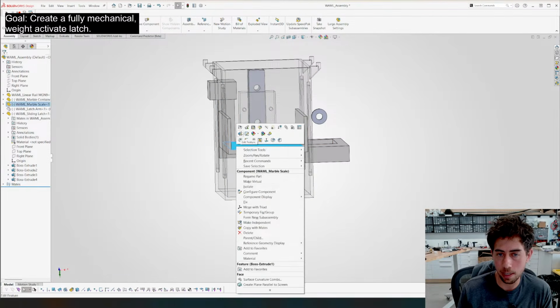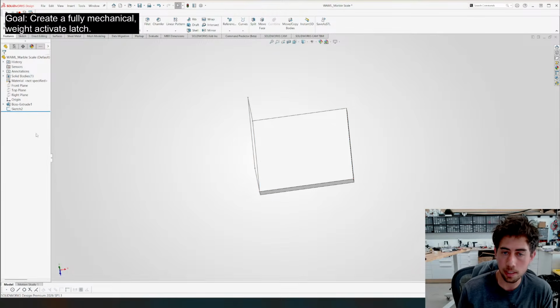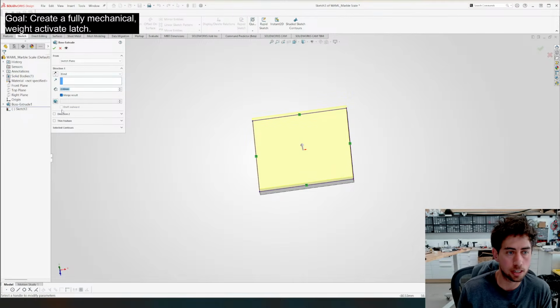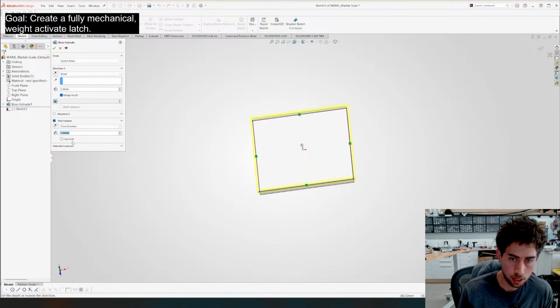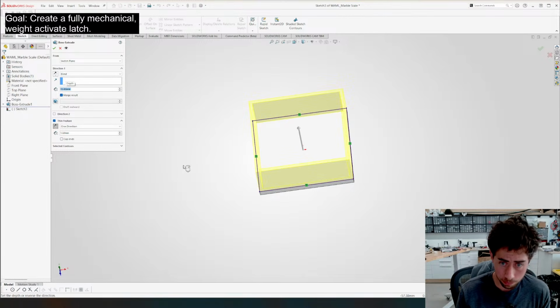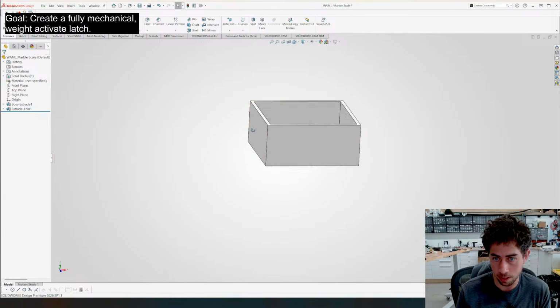Okay, so on this guy, this is our inner thing. I think what I'm gonna do with this is make this like a little inside container. So I'm gonna extrude it up as a thin feature with a 1.6 millimeter wall thickness. And now is actually a good time for me to show you why I'd be going with 1.6 over other random dimensions. We'll make that 15, 18.